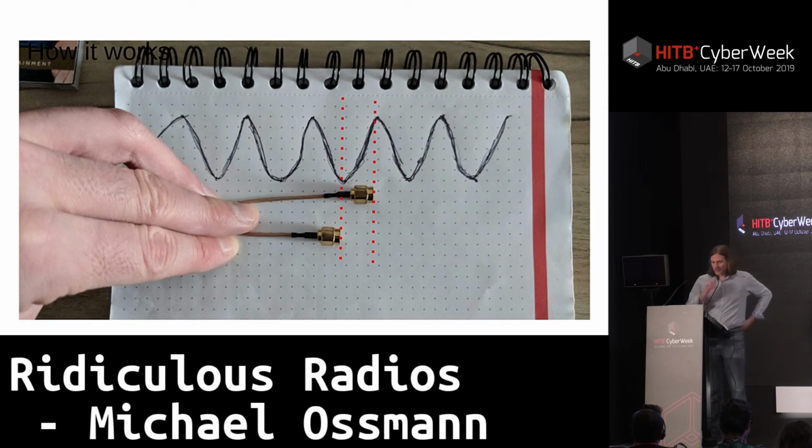Now, this is a really sophisticated plot here that Dominic drew to show how we actually introduce a phase shift over this signal. And the way we do it is with what's called a delay line. It takes a certain amount of time for a radio signal to be transferred from one end of a cable to another, right? Because the speed of light is this cosmic speed limit that we can't exceed. It doesn't happen instantaneously, but it does happen very fast, that an electrical signal goes from one end of a cable to another.